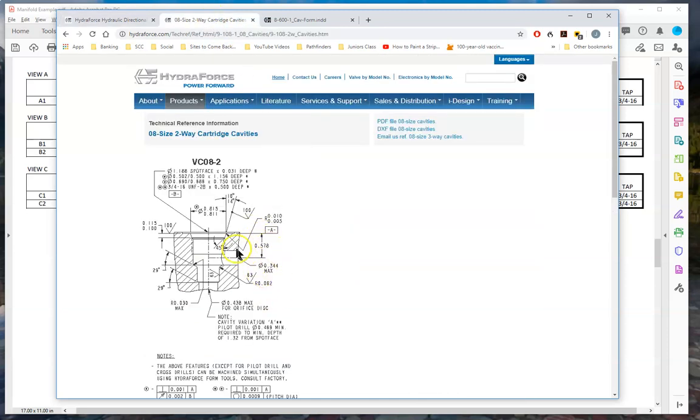It says right here that the maximum hole diameter for this should be 344 thousandths. I can either find this information off this drawing, or I can use the calculation for velocity through a line. Now, I create that hole size using that drill for my manufacturing call out there.